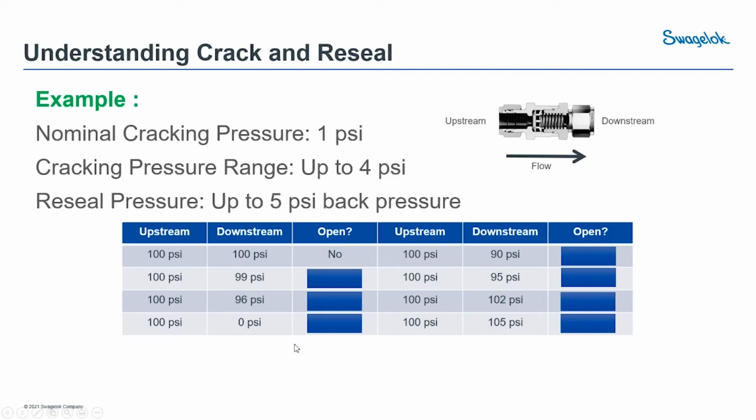I think naturally people would say, yeah, this is going to be open at that point. The real question, the answer here is maybe. And I think sometimes I like to, instead of maybe, say kind of. And the reason why I say kind of is because you're hitting the cracking pressure, and that's a spot where you first start to see the first little bits of material bubble through.